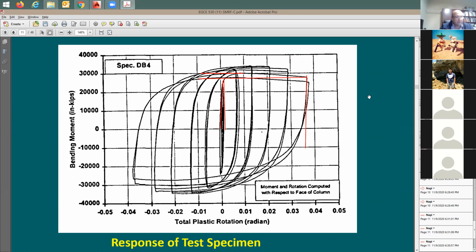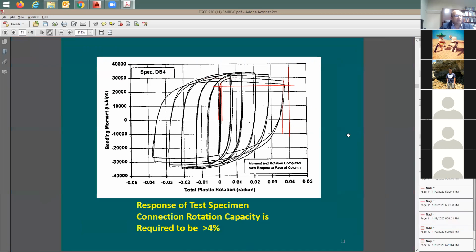Now this chart that you're looking at, it's not really lateral force versus displacement. It's gonna be bending moment versus, look at this, rotation. So I said, now I understand rotation. Rotation is gonna be the slope of the column line, if you like. And look what happened to it. This is gonna be at 4%. So this is gonna be the 4% we're talking about. And at 4%, the question is, did we drop to about 80%? I'm gonna say no. The system is still strong. So this is actually, the performance is great. Look at this. It has a great performance, if you like, right? And look at the amount, this volume here, for this area here included by this hysteretic loop. It's really big. Compare it, if you like, just to do here a comparison.